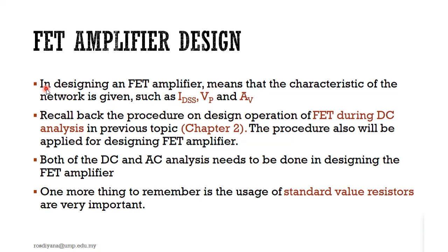In designing an FET amplifier, it means that the characteristics of the network are given, such as IDSS, VP, and AV. I hope you can recall the procedure on design operation of FET during DC analysis in chapter 2. The procedure will also be applied for designing the FET amplifier. In this FET amplifier design, both DC and AC analysis need to be done.